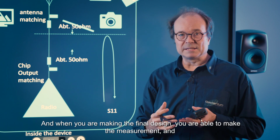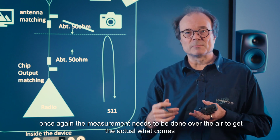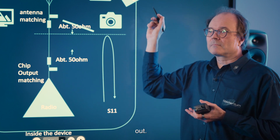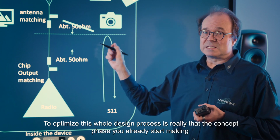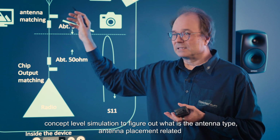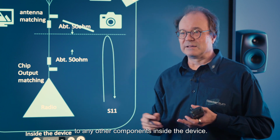When you make the final design, you are able to make the measurement, and once again the measurement needs to be done over the air to get the actual radiation. To optimize this whole design process, in the concept phase you already start making concept-level simulation to figure out the antenna type and antenna placement related to any other components inside the device.